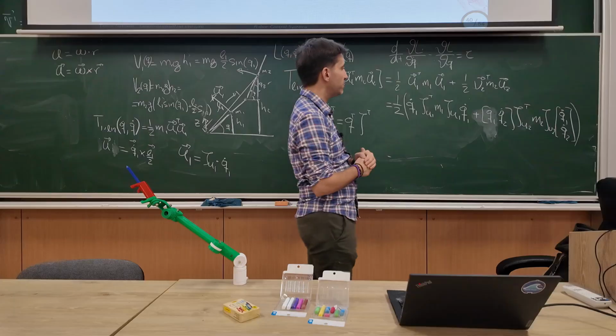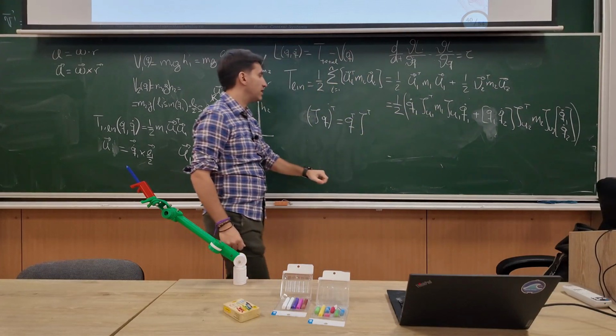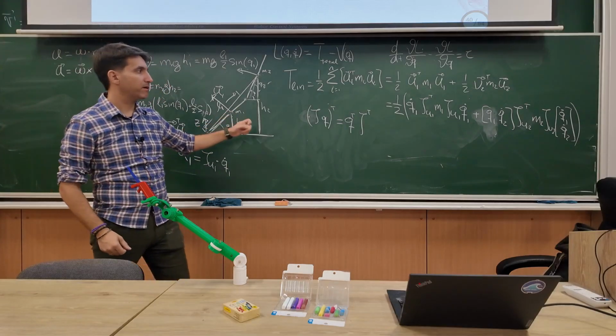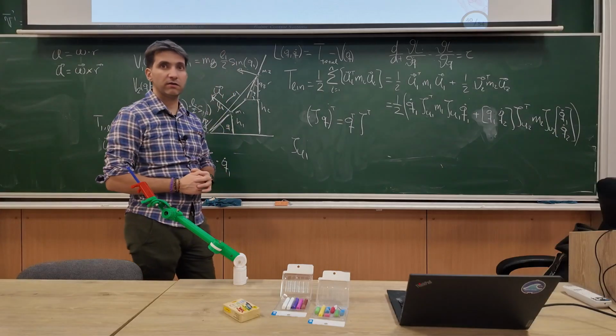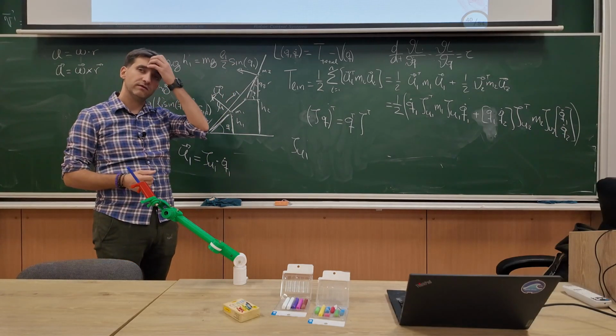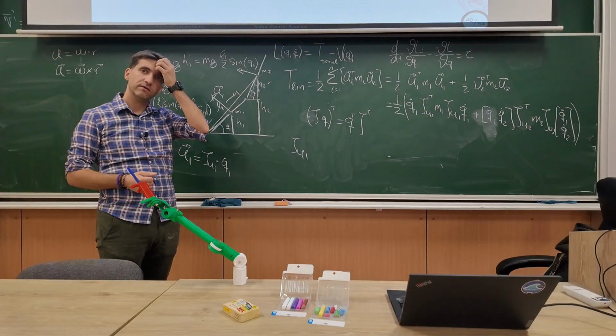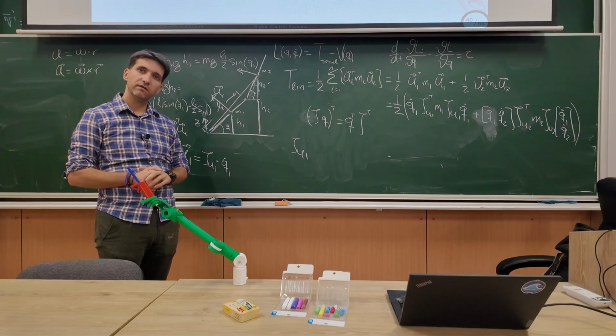The second thing is about dimensions. What is the dimension of this Jacobian if it is until mass 1, JU1? 6 by 1. Why? 6 because we have 6 degrees of freedom, and 1 because we have only one joint.